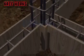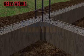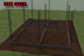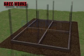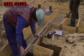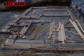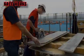Beam concreting. Beam is poured with concrete with grade mentioned in the drawings. The positioning of reinforcement should be properly aligned. Shuttering parts and connections should be arranged in a way that makes formwork removal easy and simple, prevents damage to concrete and formwork panels so that it can be reused without extensive repair.